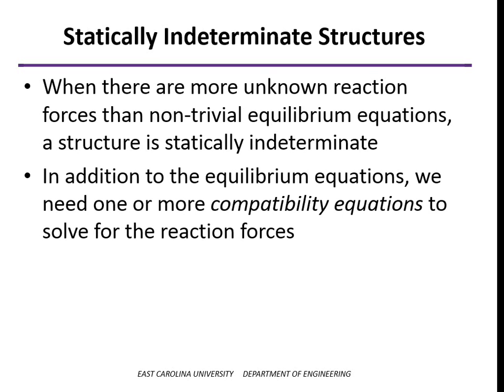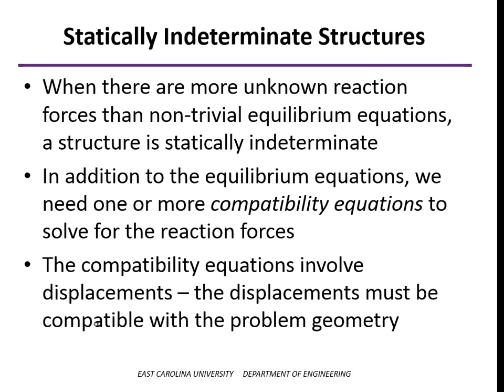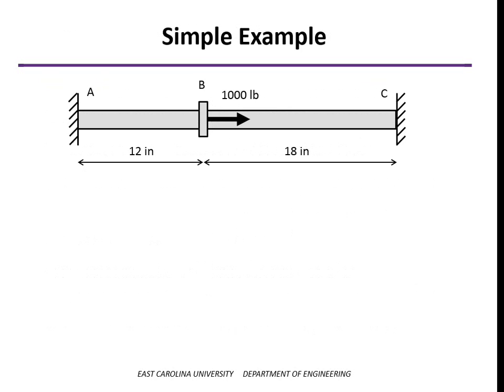And so what we need in addition to those equilibrium equations are a compatibility equation, well actually one or more compatibility equations, depending on how many extra reaction forces we have. And those, along with the equilibrium equations, are used to solve the problem. Compatibility, you can think of it as you need the displacements to be compatible with the problem geometry. And so we'll see that in this simple example here.